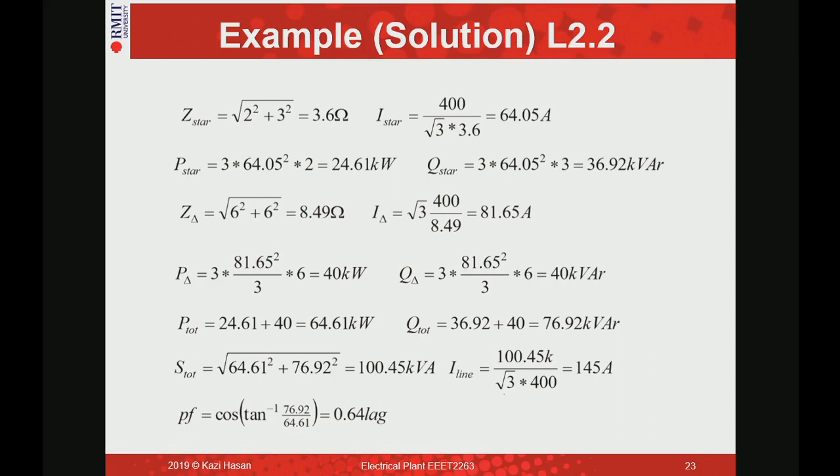Because this was the line, I phase. So that is actually I phase, this is I_P. So now I want to calculate the power I squared R, and this is actually I_P squared R, because this is the phase current. It's only one, each one. So what do I want to do for the whole circuit? Times 3. I want to write 3 I_P squared R. Am I right? Yeah. Good.